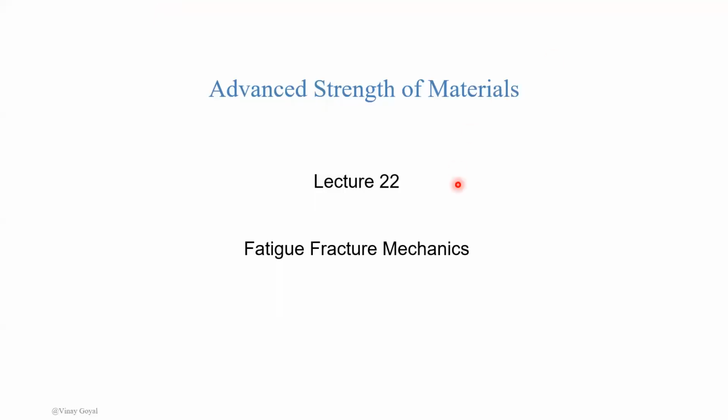The fatigue fracture mechanics here, what we're talking about is you have a crack, but then you oscillate the loading conditions, and that causes the crack to close and open, and that's going to cause a crack propagation that occurs due to fatigue.